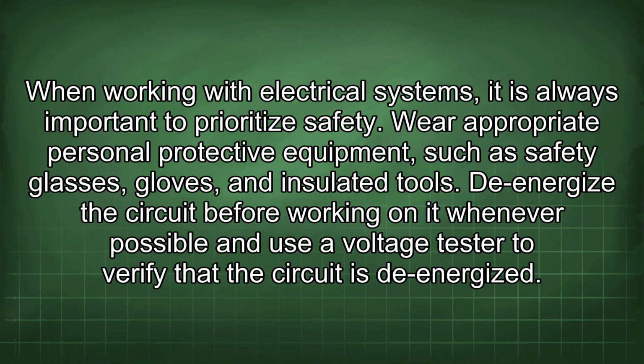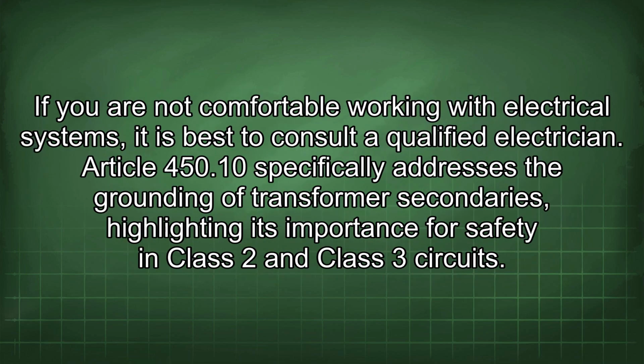When working with electrical systems, it is always important to prioritize safety. Wear appropriate personal protective equipment, such as safety glasses, gloves, and insulated tools. De-energize the circuit before working on it whenever possible, and use a voltage tester to verify that the circuit is de-energized. If you are not comfortable working with electrical systems, it is best to consult a qualified electrician.